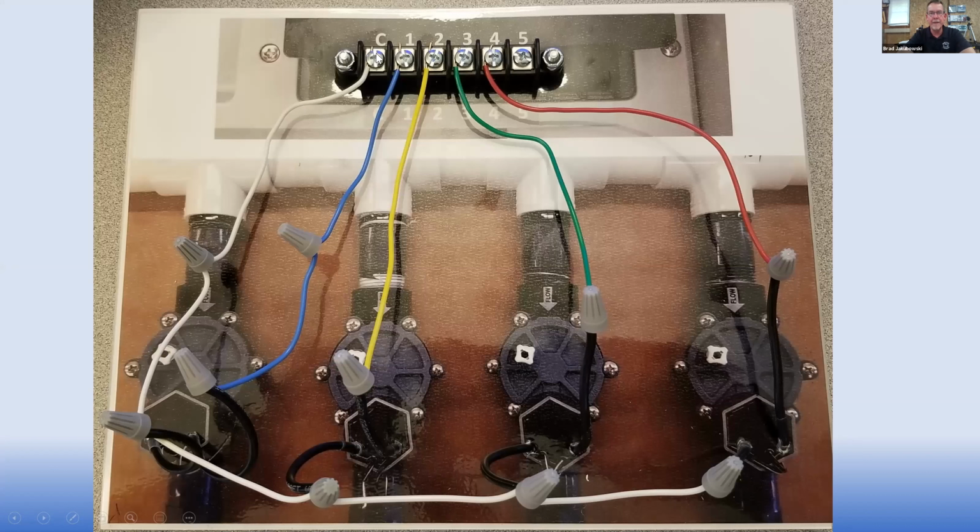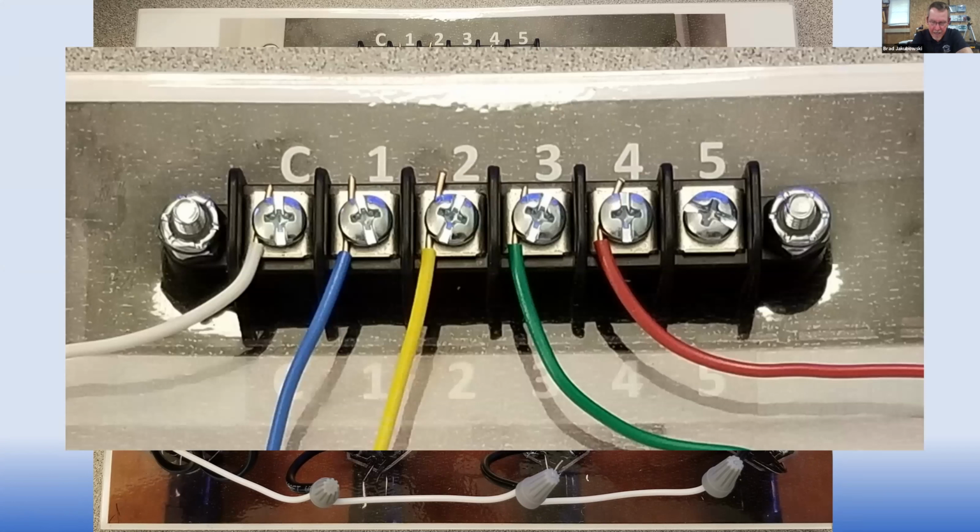Now, one of the things I wanted to share with you here is a learning moment. Maybe it's just me, but even in the Air Force, any time I try to do this, when you're hooking up wiring to a controller, you might notice all of the wires are coming in on the left side of the screw. Why would we want to mount the wires on the left side of the screw, or on the 9 o'clock side? When you tighten down the screw, it goes clockwise.